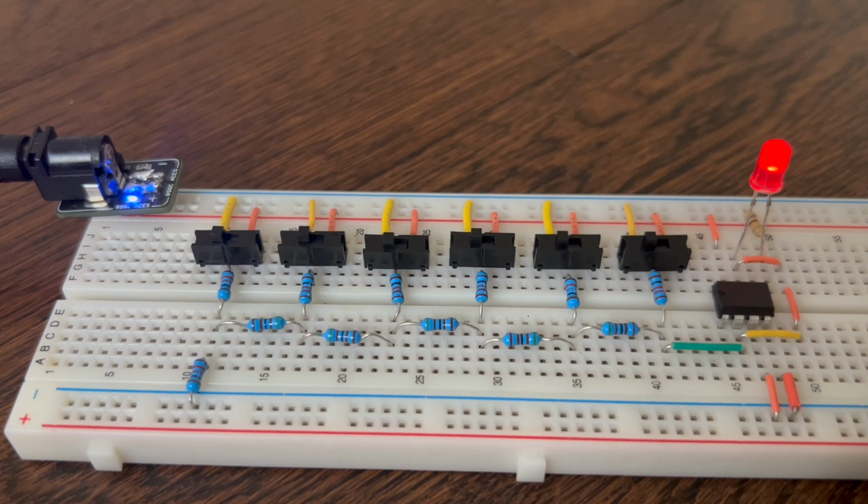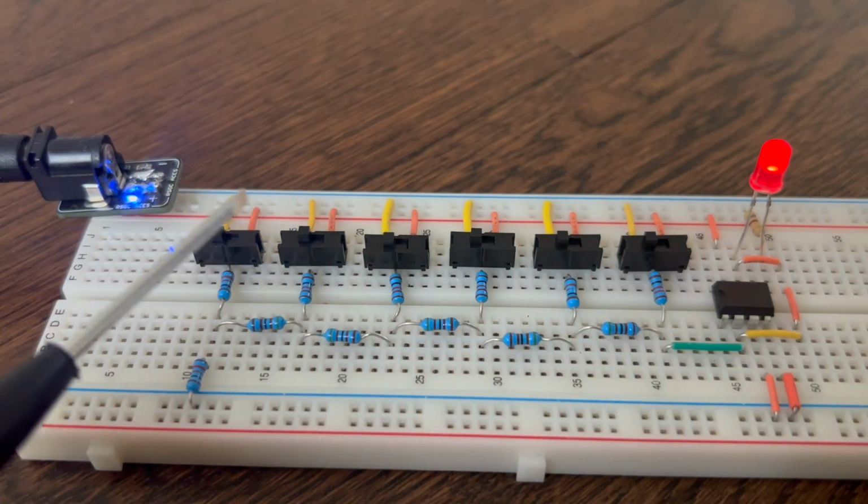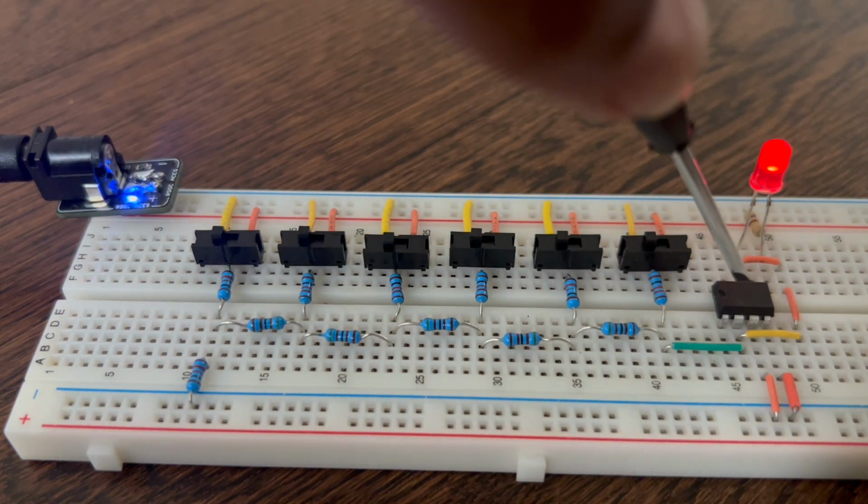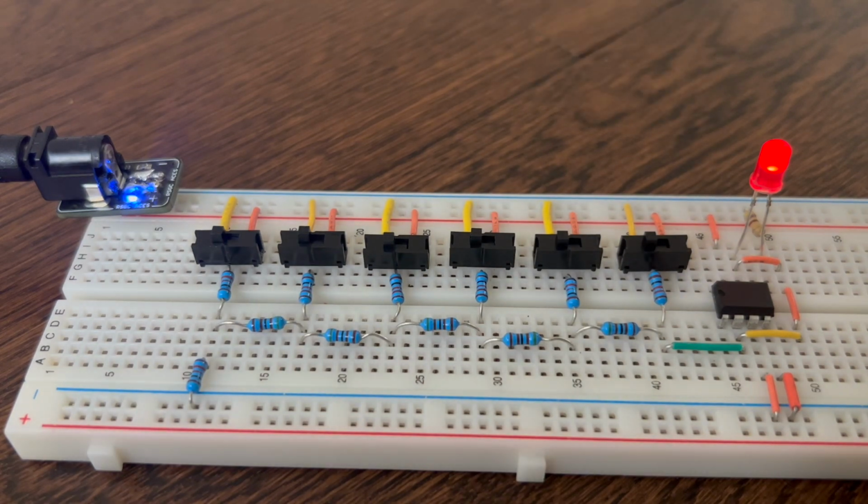And as you can see, all the switches are off, or on the left side here, and the LED is actually still on, which was not the case with our 8-bit without the op-amp. So in theory, when the circuit outputs 0 volts, the op-amp should also output 0 volts, but because the LM741 op-amp chip has some restrictions, this is not the case.